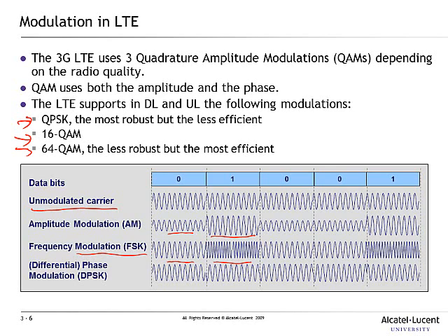In the case of phase shift keying, which is the last diagram, we keep the amplitude and the frequency constant, but we keep changing the phase. Okay, and you can see here when we have a 0, we transmit the original modulated carrier. When we have a 1, as in this case here, you can see that there's a phase change that has occurred. Okay, there's a 180-degree phase change that has occurred to the carrier, and that is referred to as differential phase shift keying.